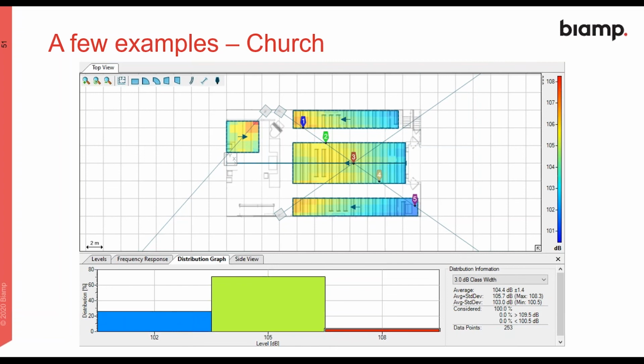So this allows you to point the loudspeakers and then adjust accordingly to make sure that you get the correct coverage and the correct performance before you even go to the site, or even if it's built. But needless to say, a site survey is always great because this plan or drawing may well give you a good idea of how the space is physically, but it may not always show you, for example, pillars or spaces in the room where something else is there. So it's a good idea to always do a site survey or get photographs as much as possible, or drawings of how the room will be if it's not built yet. But this gives you a great starting point.